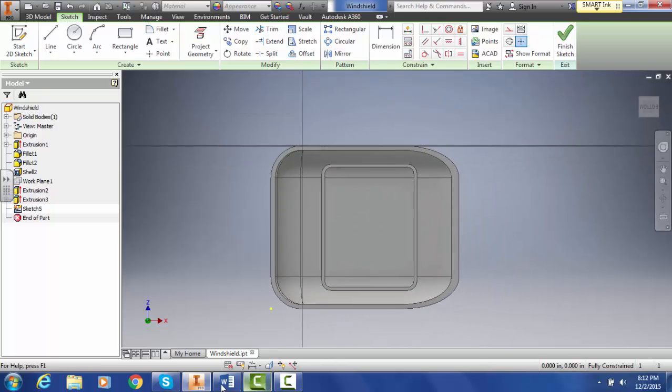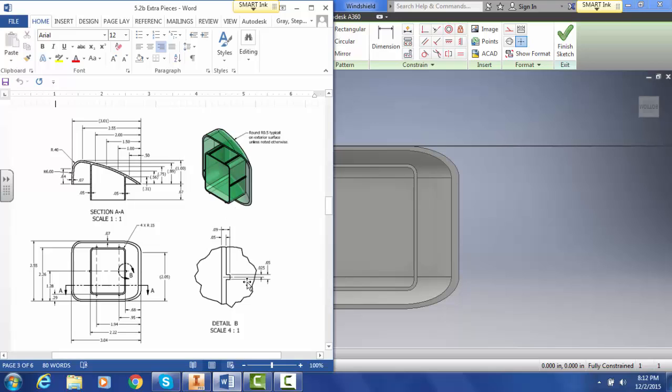My rectangle needs to be, and they give us the dimensions actually over here, it's 0.05 wide, and this way I know that the edge around is 0.05, and then all the way over is 0.09, so I have to subtract those two to find the height of this little tab, and that's going to be 0.04. So that's what we need to create, a 0.05 by 0.04 rectangle.